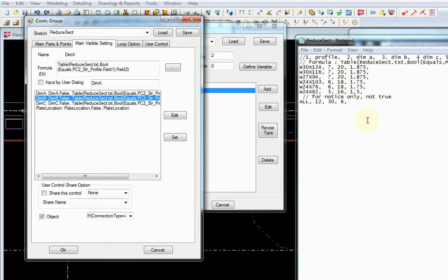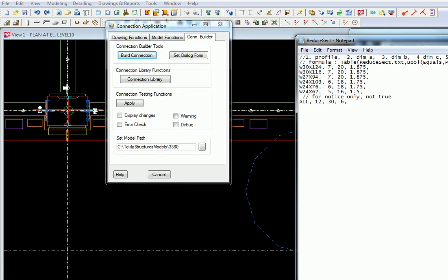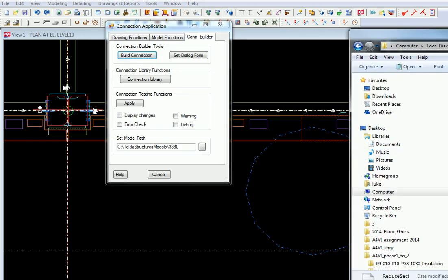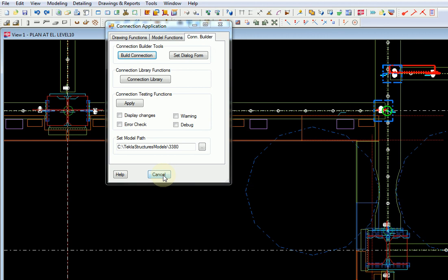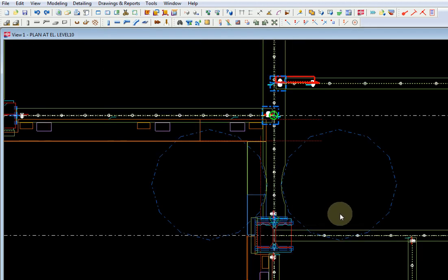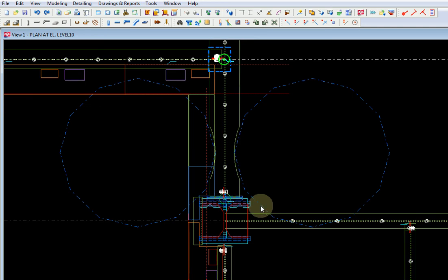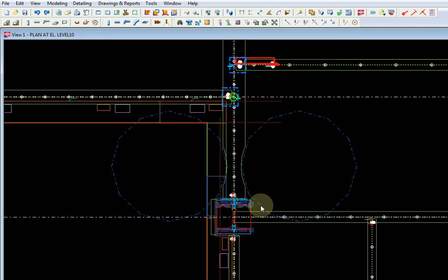The connection automatically reads the table and gets the value, then pushes this value to the connection macro, then applies the connection. So the connection becomes intelligent. It reads the table, the formula, and the rule you set up, then automatically determines which connection to use and what detail values to use to create those connections.